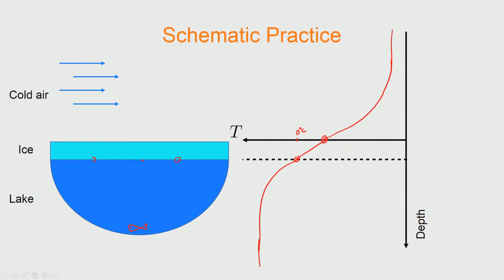Then you can estimate what would be the heat coming this way, and what is the heat going. The first one would be, for example, the heat transfer coefficient h inner, into T bulk minus T m, where T m is 0 degrees centigrade. And here it would be the thermal conductivity of ice into delta T by delta x, where delta T itself is given as T m minus T s.